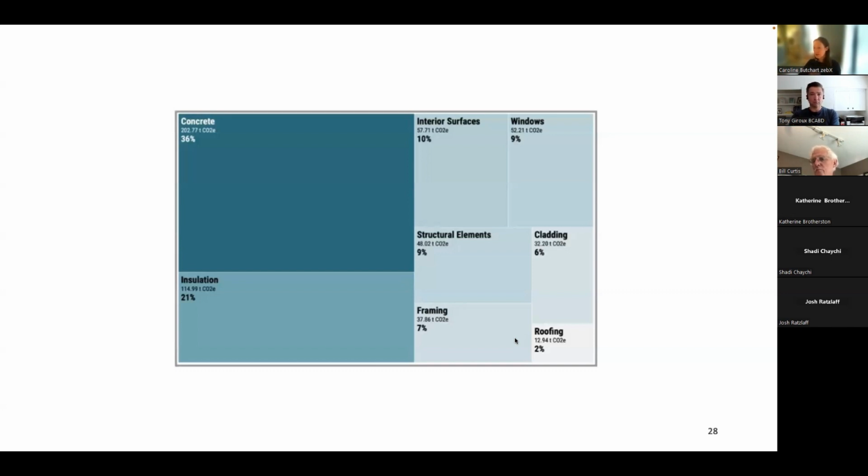So that's moving space above ground, eliminating basements, or eliminating some of the basement volume, and switching out foundations. So some of the lowest carbon buildings that we're seeing are eliminating the basements entirely and swapping the generic strip foundations to pier foundations, which use a lot less material but do the same thing.